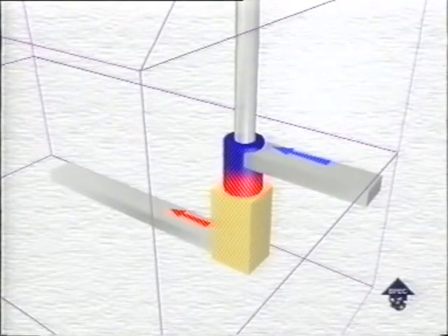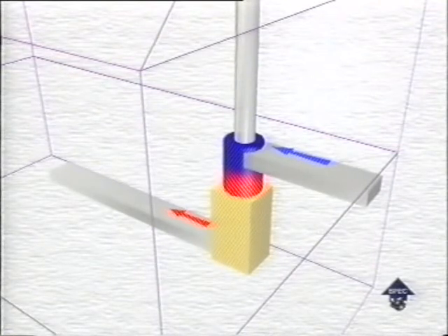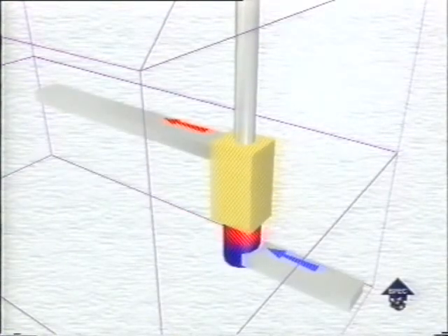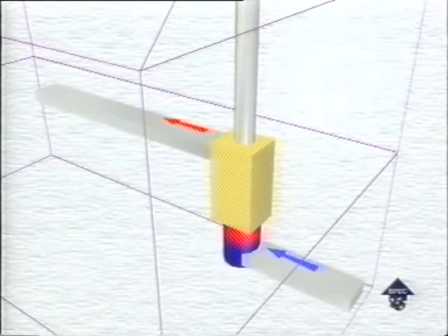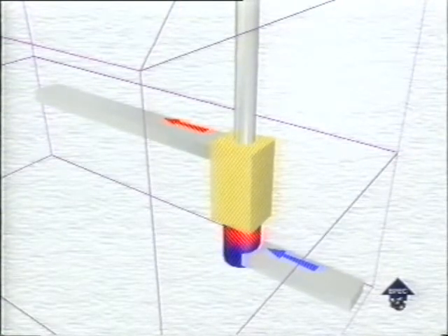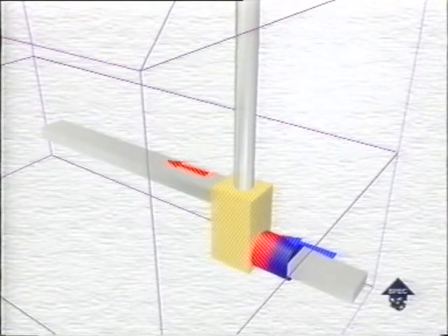The fan can be installed above the heat exchanger so that the warm air is blown downwards and distributed from the bottom. Installing it below the heater delivers the air upwards. This might be a useful configuration in a basement, for example. And if the fan and heater are side by side, the warm air is delivered horizontally.